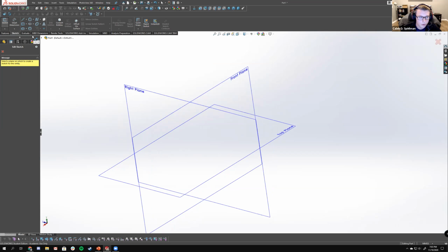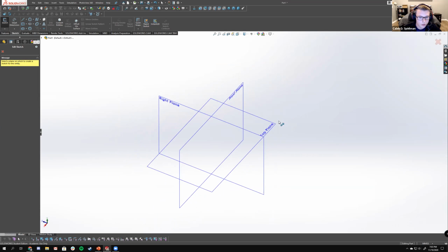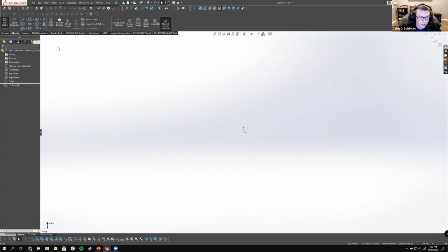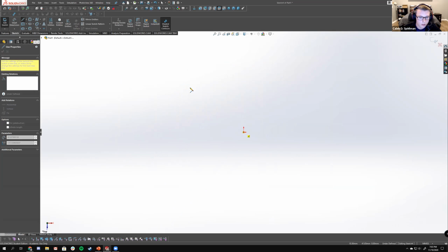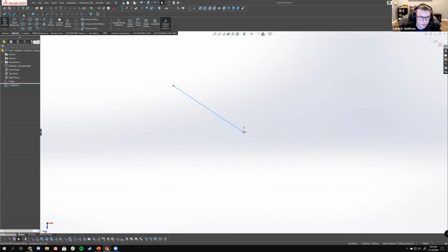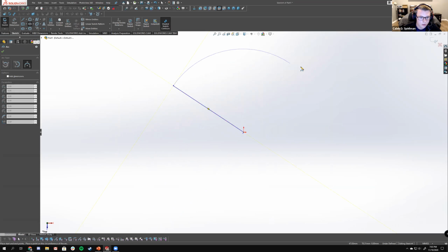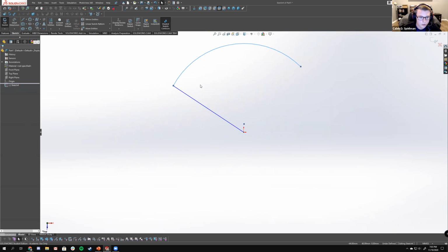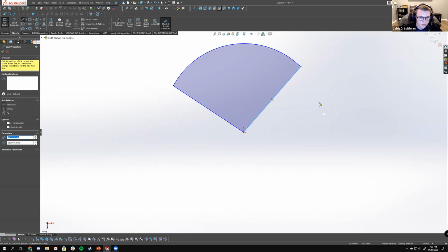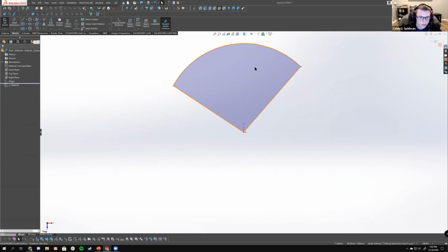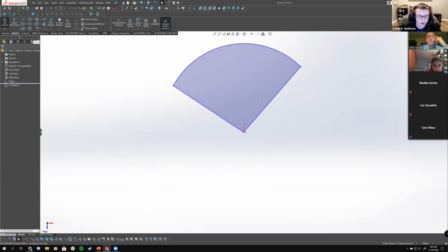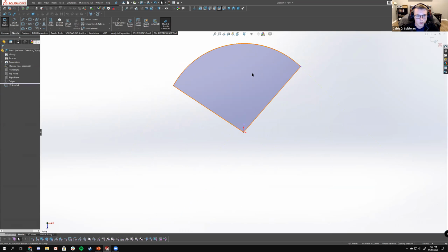So if I click in the upper left here, I can select the sketch tool. I can click on a plane and start constructing contours using sketch entities. This line is just a sketch entity. This arc is just a sketch entity. It's essentially its own entity. That's really it. So here now, you can see in blue, it'll show whatever our contour is as blue.